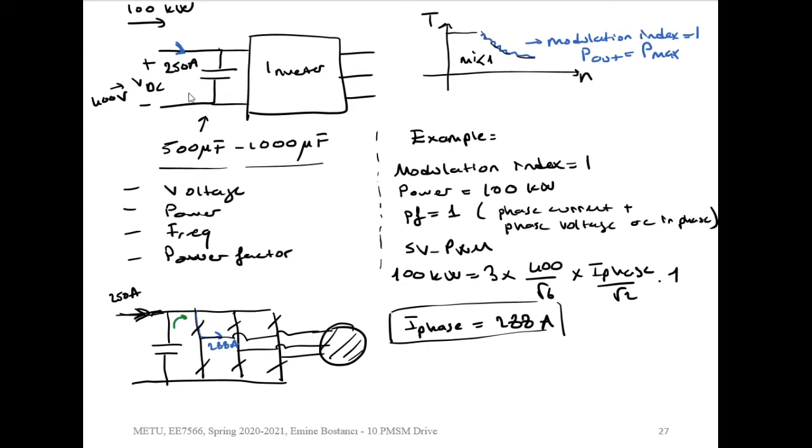If you want to have a constant DC link voltage, what you can do is place here a very big capacitor, so it doesn't fluctuate much. This could be one solution, but on the other hand, we don't want a very big capacitor, and we want to implement the minimum possible capacitor which is still fail-safe.